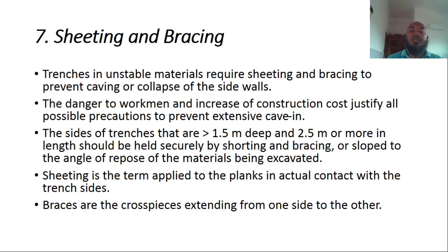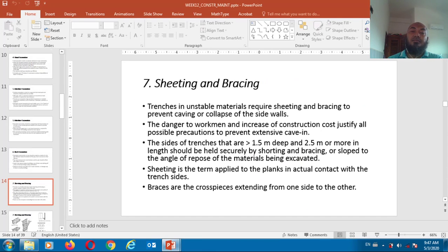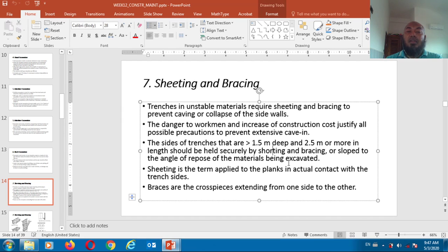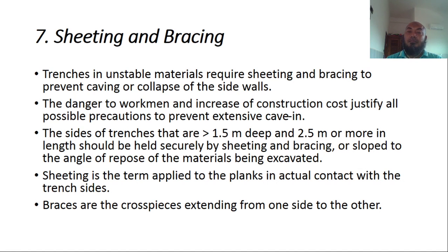The sides of trenches that are more than 1.5 meter deep and 2.5 meter or more in length should be held securely by sheeting and bracing, or sloped to the angle of repose of the material being excavated.